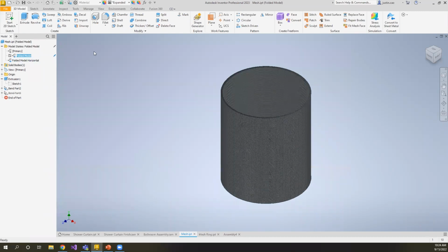The only thing that model states, I haven't figured it out, and I don't think it can handle, is if you do appearance changes. So the last customer I had, they wanted to show different colors for different types of fabric that they used. That was something that we couldn't figure out for the appearance. We could do it with the materials, but then you have that material association with it. So maybe you have to create a unique material, a unique color, and then you could apply it that way. That was the workaround that we figured out for it. So that's the only inconvenience that I've seen so far with model state. You can't assign appearances and they carry over like that.